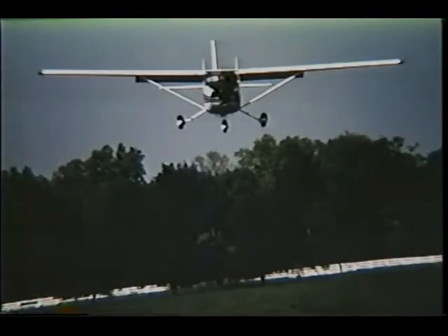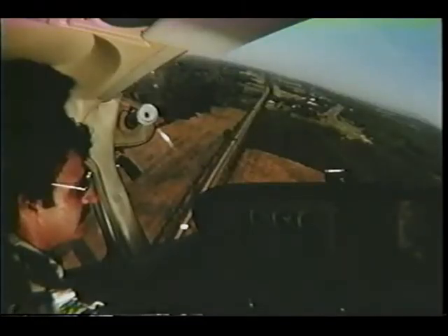There's one more thing I'd like to mention before we move on to another subject, and that is that the manufacturer's recommended final approach speed, or if not available, 1.3 VSO, is an airspeed to be flown on short final only. Remember, however, that until you're on short final, you're probably still maneuvering. By that I mean you are banking and turning, and you want to be at a higher airspeed than 1.3 VSO to make sure you can handle those banks, as well as any turbulence and wind gusts with a comfortable margin. Wind, by the way, is another major factor that can result in landing long.